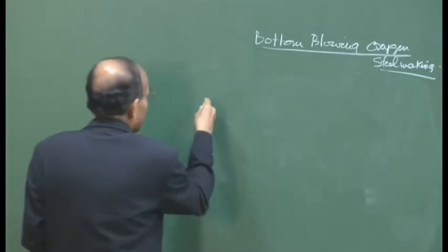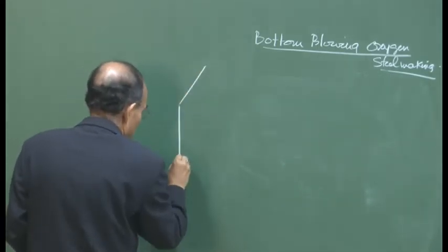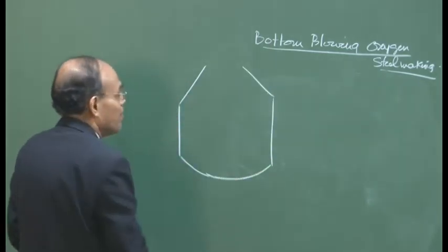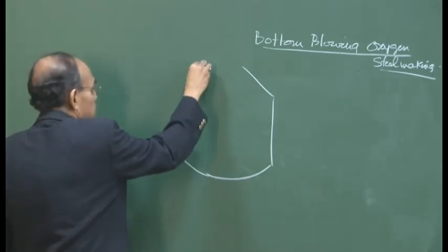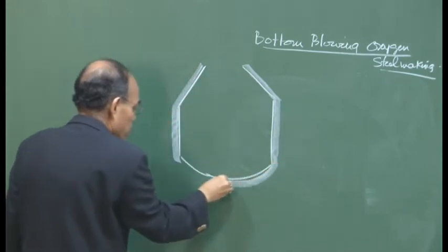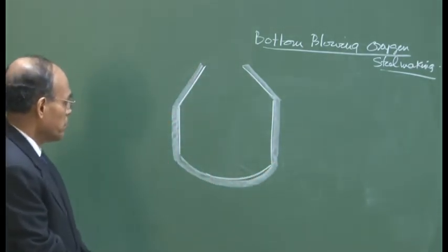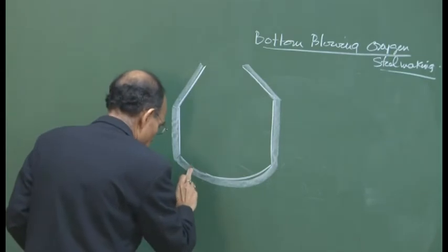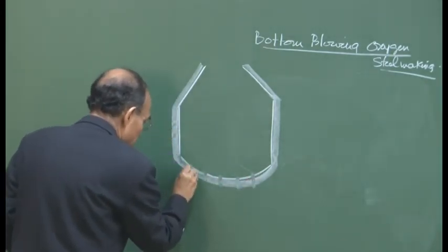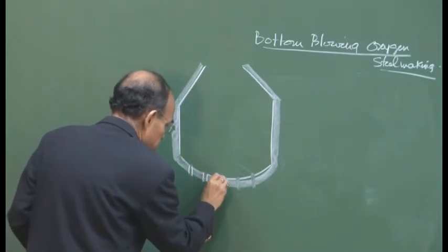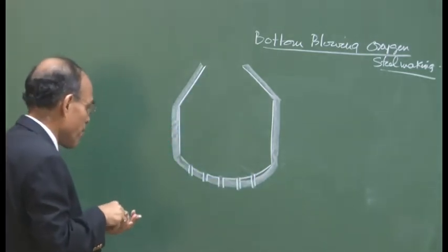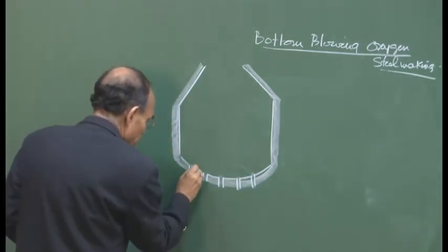So, it is the same kind of vessel that one would use, that pear shaped vessel which is our trademark steel making vessel. Okay. So, that is the vessel geometry, and now when you have a bottom blowing steel making process, you have tuyeres here, but these tuyeres, as I say again, are not the same as those used by Henry Bessemer long time back.